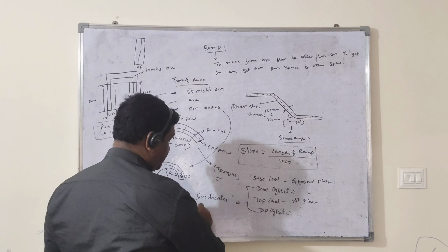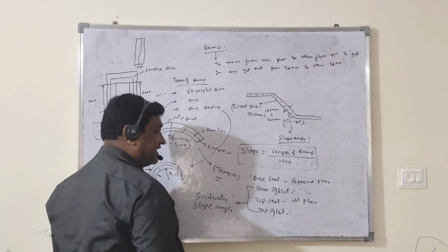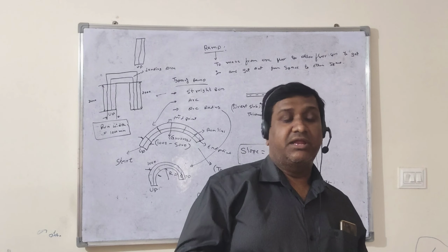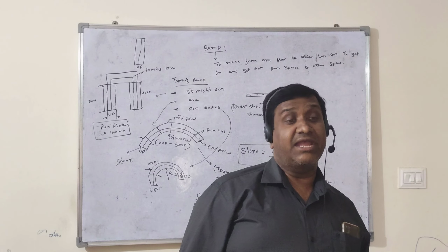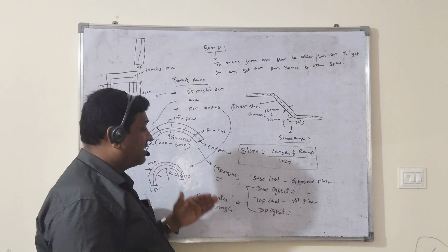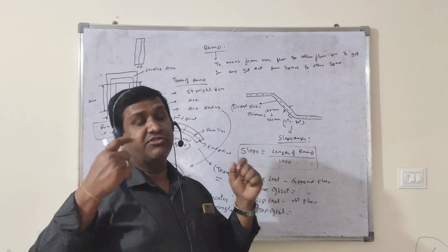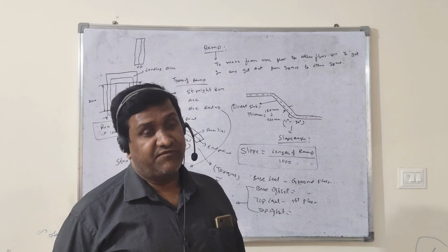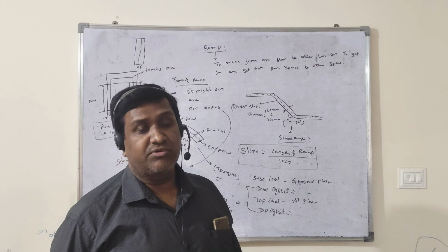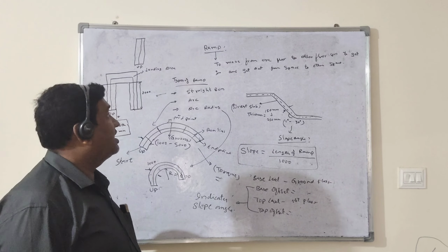They indicate the slope angle. If you change any base offset or top offset of the ramp, the slope angle will also change. Based on that, we can work out the ramp. Here also every ramp will get a railing automatically. If you require the rail, you just continue with the rail. If you do not require the rail, you leave it out. Like that, we are going to design this ramp in a project.